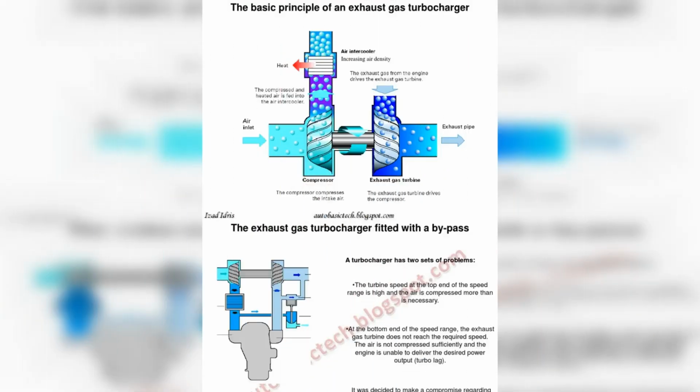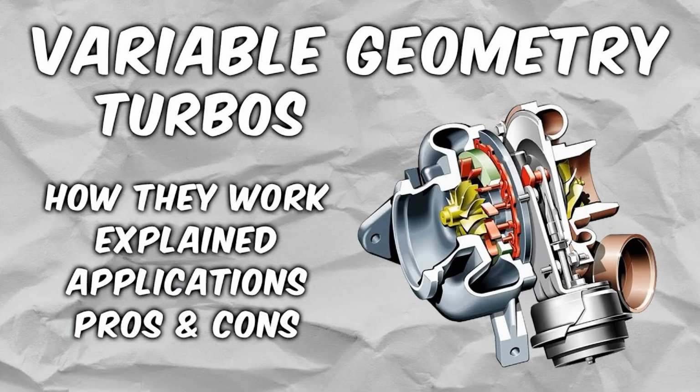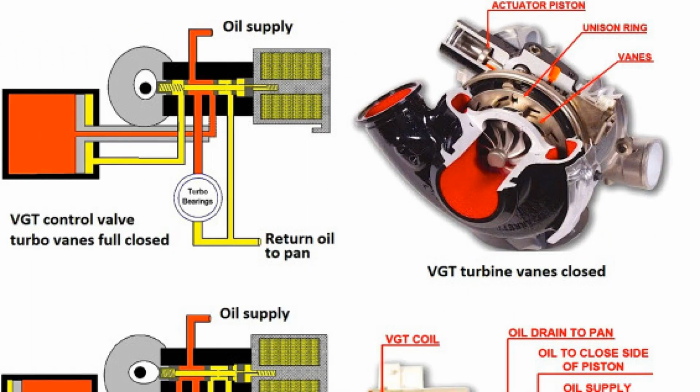Possible malfunctions. In conclusion, understanding the principle of operation of a variable nozzle turbine, or VNT turbine, is essential for optimizing turbocharging efficiency. By addressing the limitations of traditional gas turbochargers, VNT technology enhances performance across a broader range of conditions. We've explored the design of these systems, identified common fault symptoms, and discussed the importance of regular cleaning and adjustment to maintain optimal functionality. By keeping these factors in mind, you can ensure that your turbocharging system operates at its best, delivering improved power and efficiency.